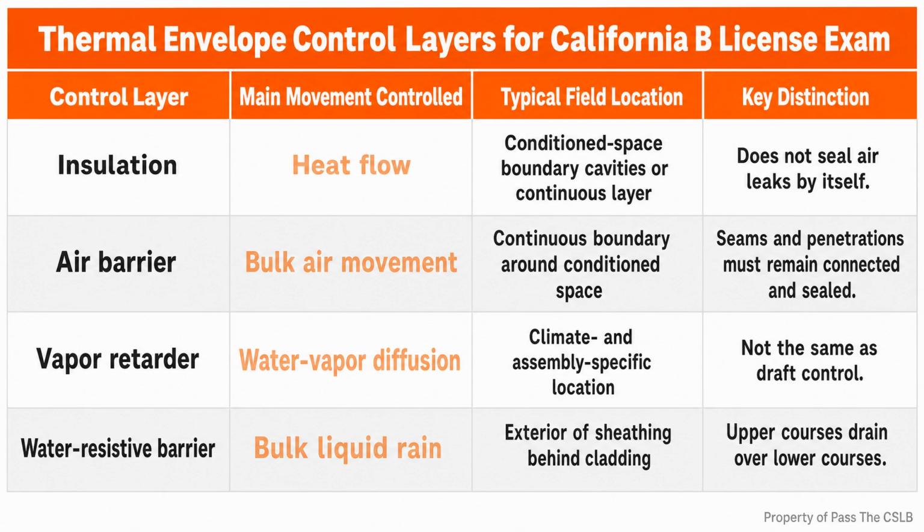When project compliance documents call for quality insulation installation verification, the sequence has another hold point. Do not let drywall or another finish conceal the work before the required field verification is complete. I treat that as a release decision, not as a last-minute inspection request. The crew needs to know the hold point before material and labor are scheduled.